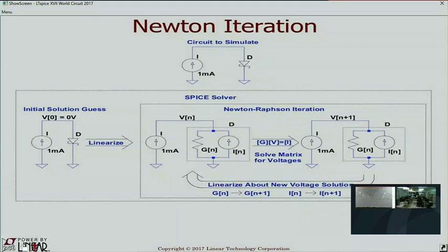Now, for a transistor, these aren't conductivities, but transconductivities. Transconductance is basically conductivity at a distance. Conductivity is the coefficient of current you get between two node voltages, depending on how much voltage you have between them. If you look at the voltage multiplied by the conductivity coefficient, you get the current through that. That's what conductivity is. Transconductivity is the same thing, but at a distance. It's the current between these two nodes for the voltage between these two nodes. That's conductivity. So you replace every nonlinearity with Norton equivalent circuits and Norton equivalent transconductance circuits.